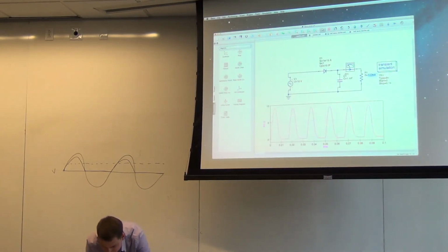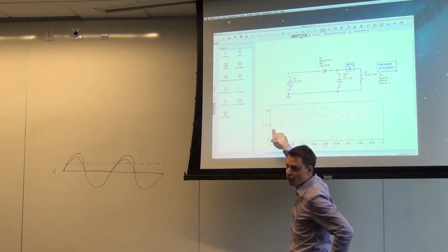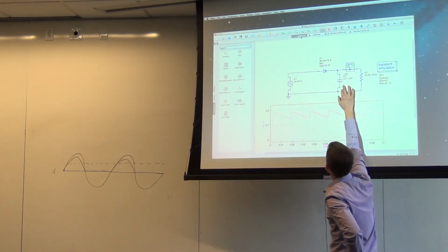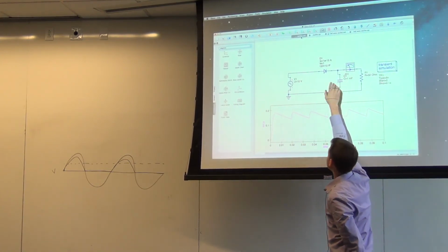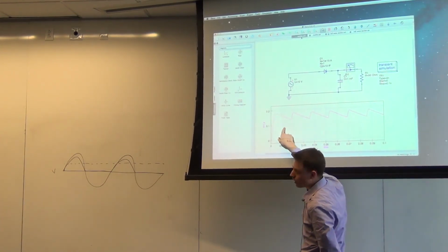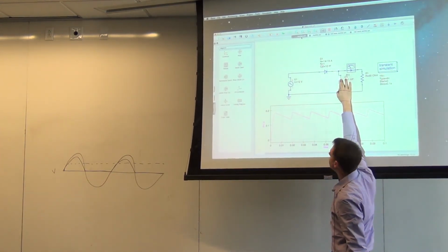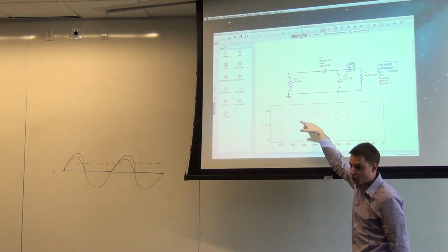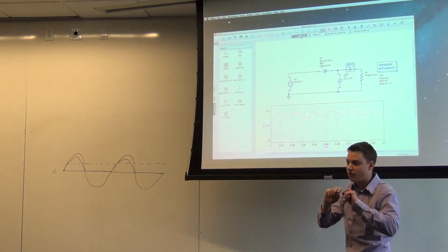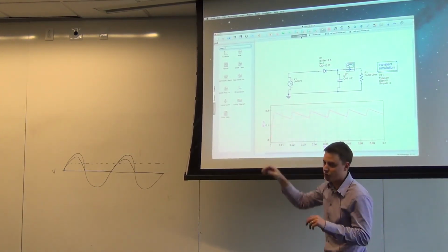Oops, whatever, let me just change it back. Okay, so the current starts following the sine wave at first. But essentially what happens is, when this is first happening, you build up charge here. And then when it goes the other way, and even at first, before it falls off, when it starts falling off, the voltage is lower than the voltage across this capacitor here. And so the capacitor will start to supply the current itself. Supply the voltage, rather, that causes that current. So you'll get a current. And the bigger the capacitance here, potentially the flatter this will look, because you'll store more and more charge.